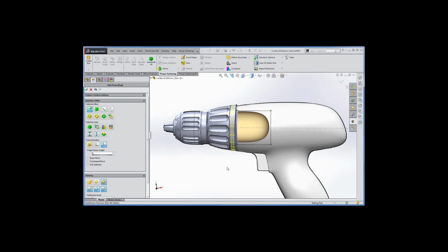And now I'm going to select those edges, and I'm going to double-click near an edge here. That's going to give me a loop rather than a ring. I always get this confused. So I double-click here, and I can always check down at the lower left. It says 4 edges selected. So I know I'm good.